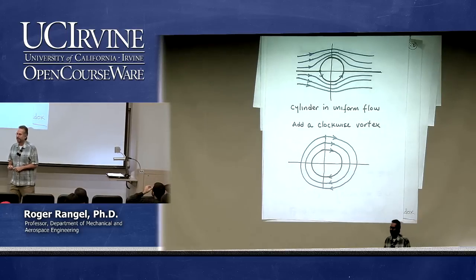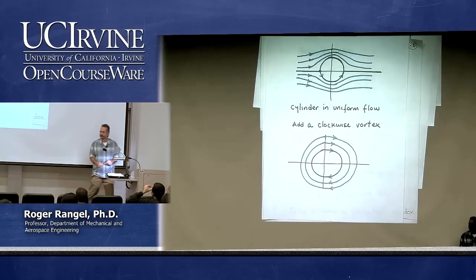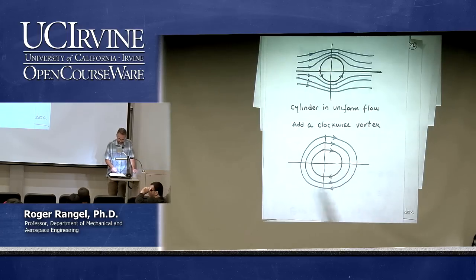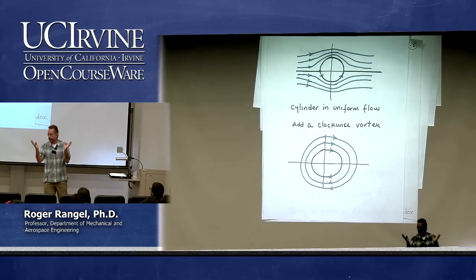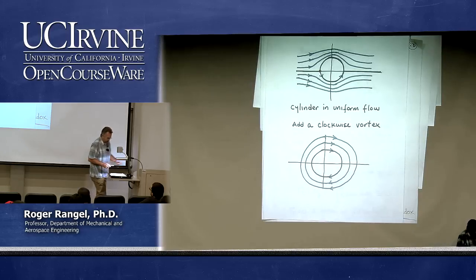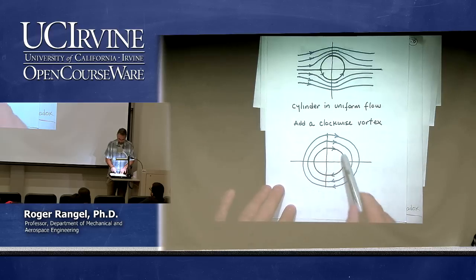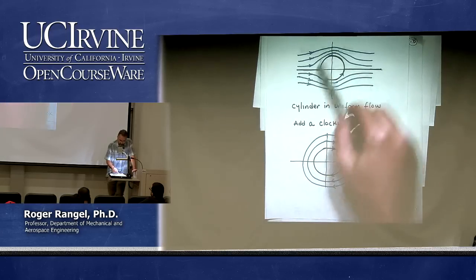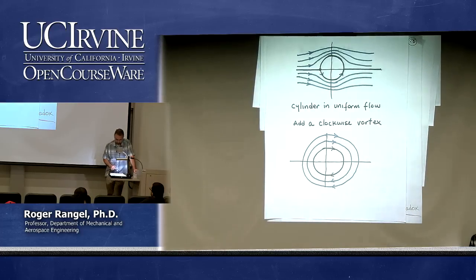They'll be underneath the shape. Why? Because your vortex streamlines going underneath it are opposing direction of the uniform flow. Correct. So in fact, I drew here in brown the cylinder, because when I add this vortex, I'm only concerned with what's going on outside the cylinder. I could also have drawn additional blue circles inside, but I don't care about those. So I just look at the one on the surface, and like he said, I'm now adding a velocity in the clockwise direction on the surface of the cylinder.